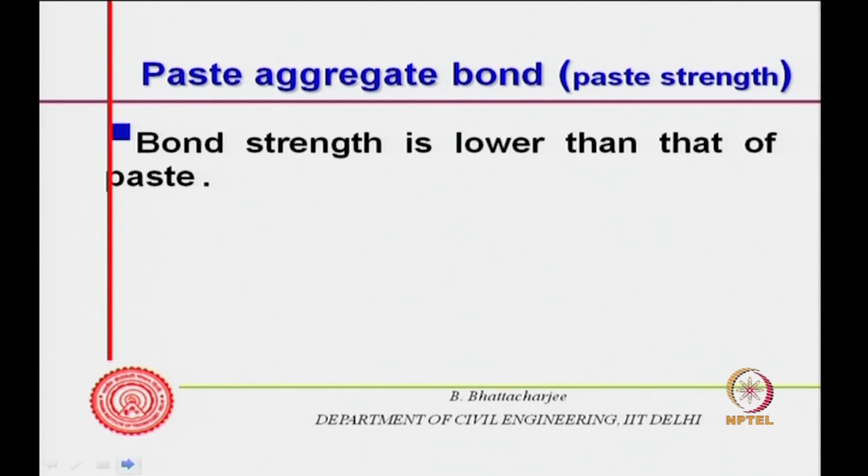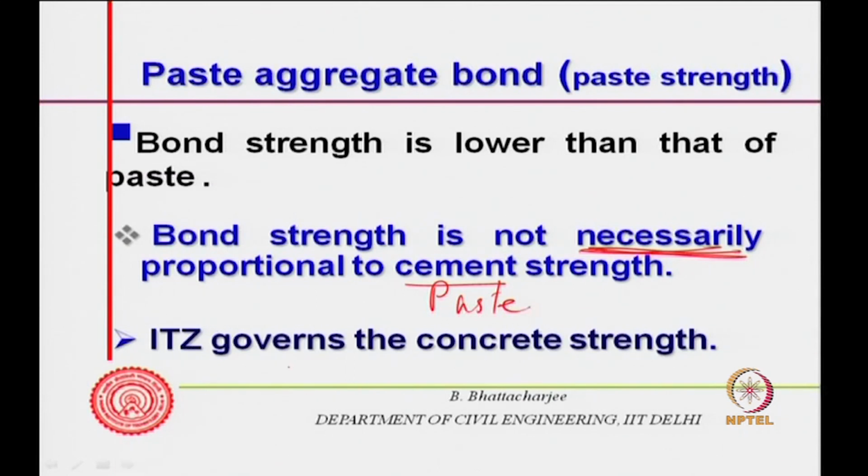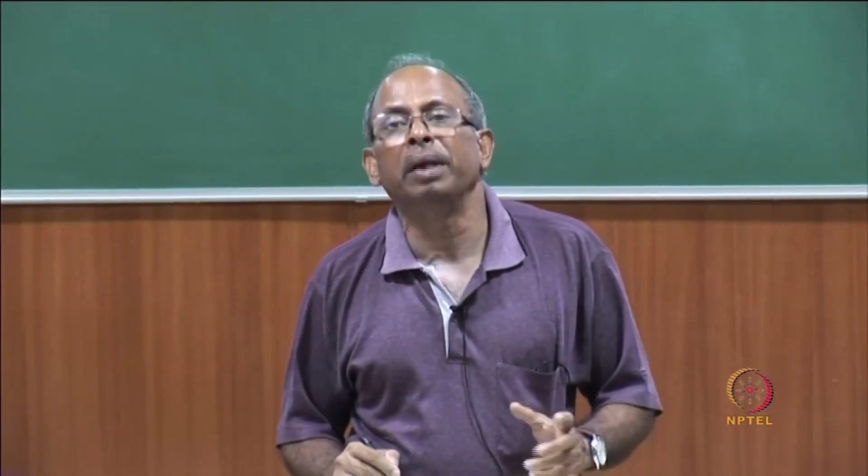Bond strength is lower than that of the paste, that of course we have seen, and bond strength is not necessarily proportional to cement paste strength. That one must understand. ITZ governs the concrete strength, that is what we have seen. So, the bond is very, very important.